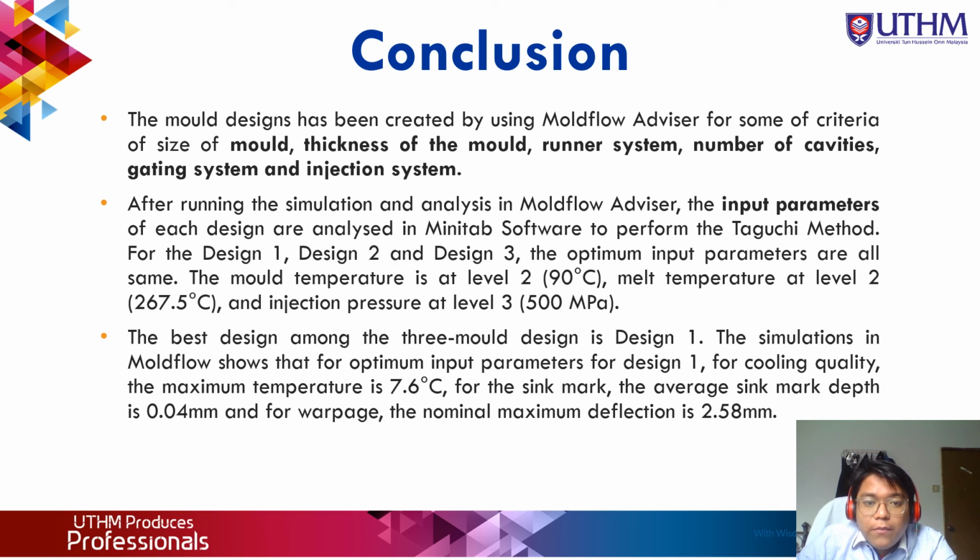The best design among the 3 mold designs is design 1. Simulation shows that optimum input parameter is for cooling quality, the maximum temperature is 7.6 degrees C. For sink mark, the average sink mark depth is 0.04 mm, and for the warpage the nominal maximum deflection is 2.58 mm.